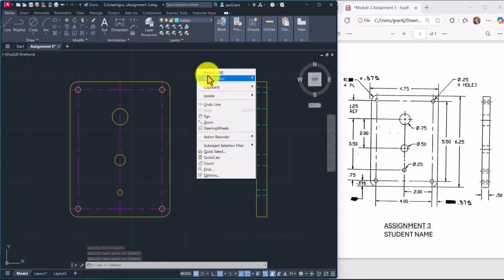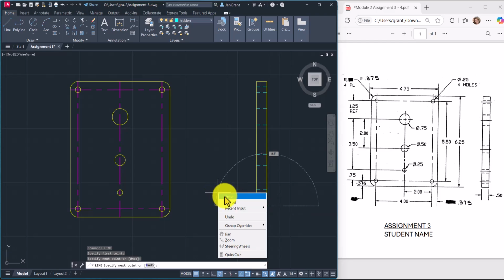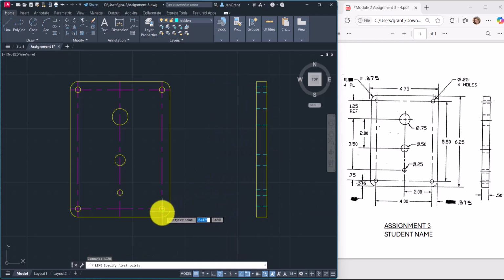And the last one here is that small circle in the corner. I want to grab that one, and we've got these lines here. You can pause the video if you want to take a little bit more time to do that. Okay, so those are the hidden lines that represent the holes in this 0.5 thick, potentially metal plate.